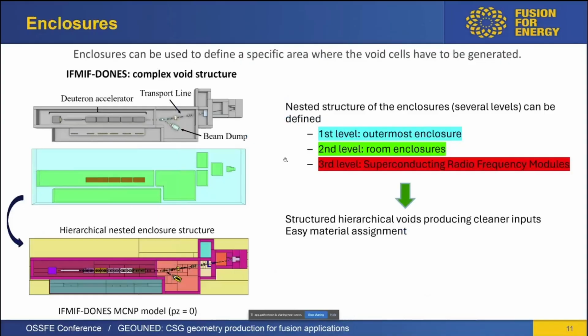It also has, and this is a very good feature, what's called enclosures, and it separates this tool from all the rest. As I said, there were some free and open source options, but less maintained at the time, and also proprietary software, but none of these had this option of enclosures. So what this basically allows us is that when we have to produce the void space, so all the rest that is not explicitly represented in the CAD model, we can separate this void production per rooms.